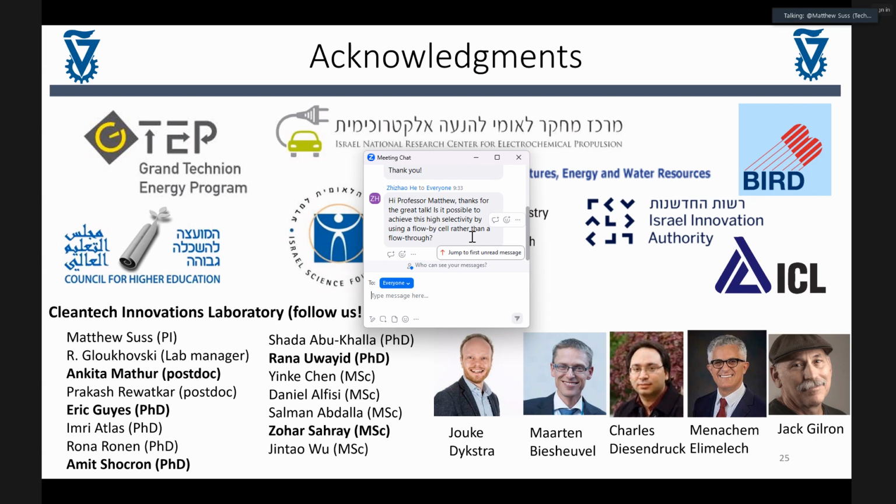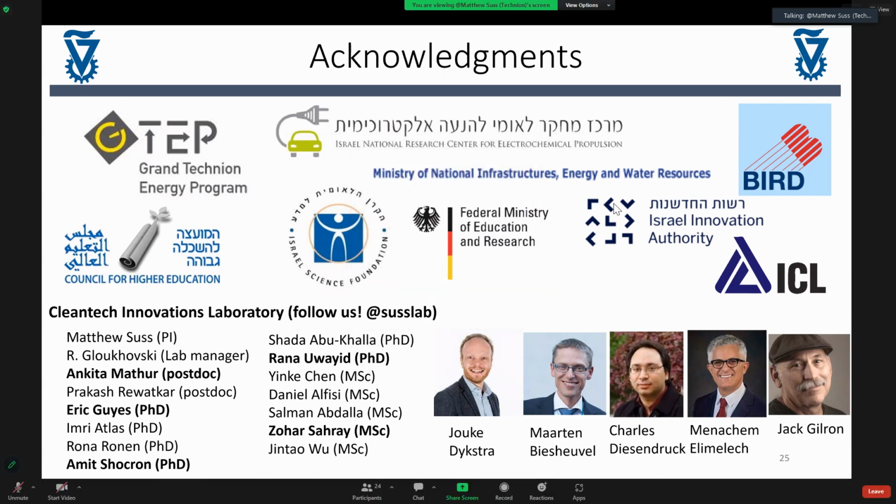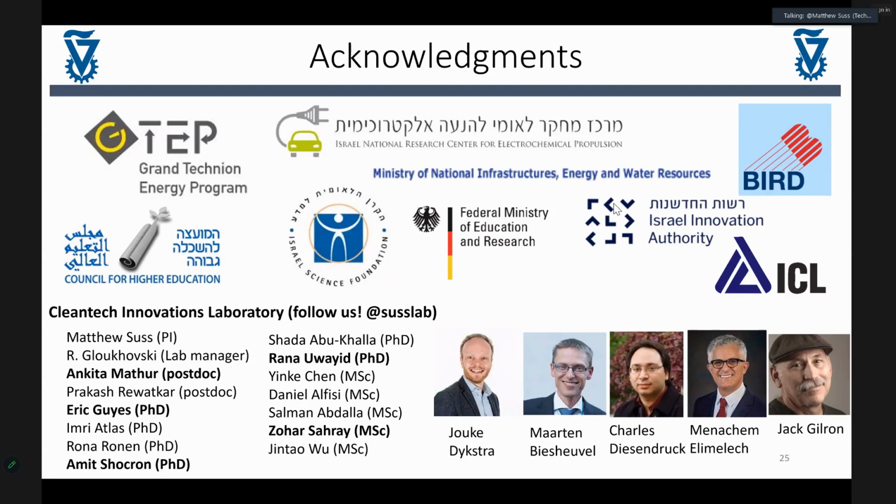Yeah, so it depends on the separation. There are some interesting things about a flow-through electrode cell, like the pH differences inside the electrodes can be much stronger than what you get between the electrodes. So you can access more extreme pH variations if you're flowing the feed water through the electrode pore space. If you have these pH-sensitive separations, like with weak acids, you might want to try to understand what flow-through electrode gives you versus flow-by, and possibly there's some enhancement there. For the other separations, like the divalent selectivity, I don't think the flow configuration is so important.